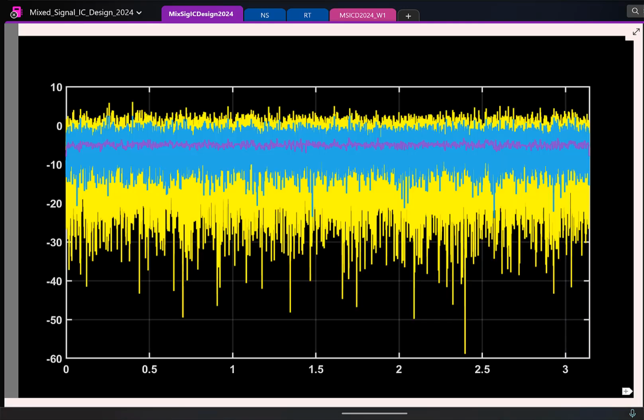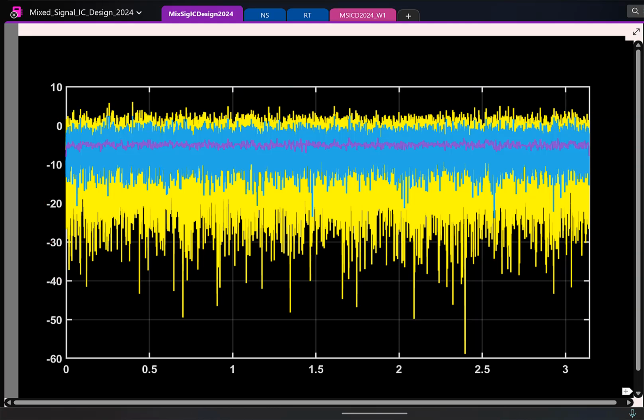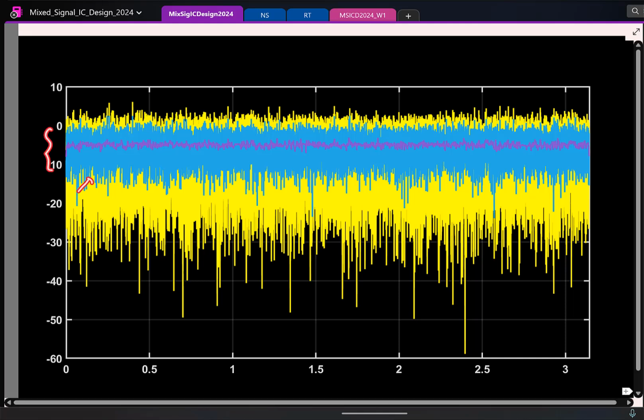So what I have done here is I have generated a random sequence in MATLAB, which is supposed to have a flat power spectral density. I didn't do any averaging and directly did this magnitude squared, and the thing I get is yellow. As you see, there is a lot of variance over the expected value. Once I average it about 4 times, I get the blue one. Once I average it 10 times, it's fairly constant.